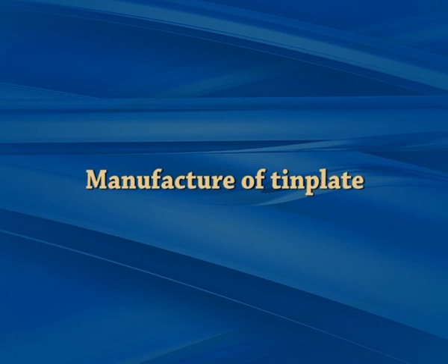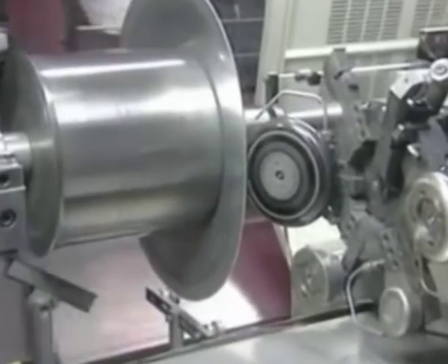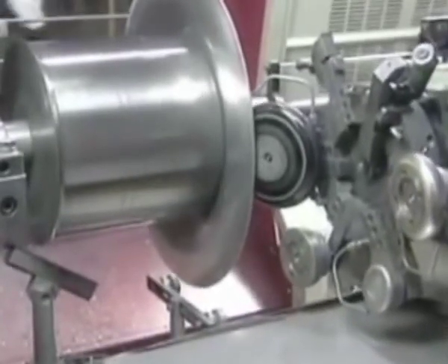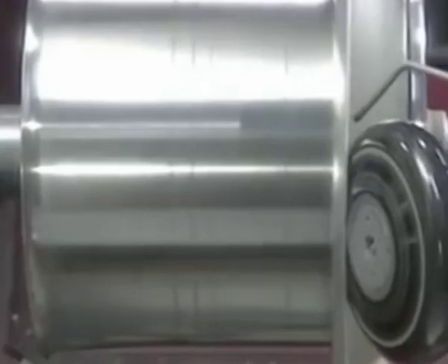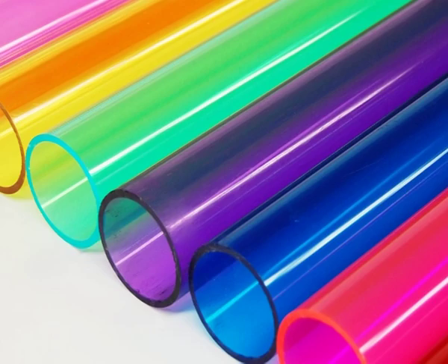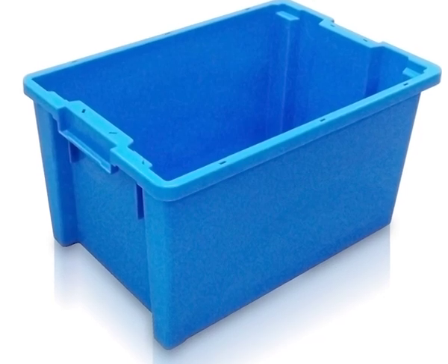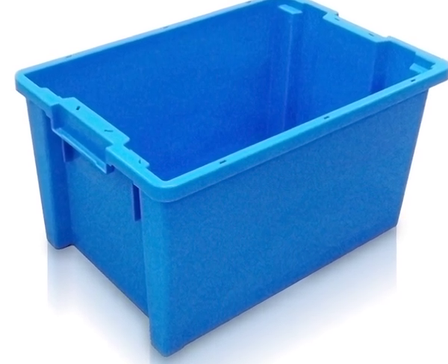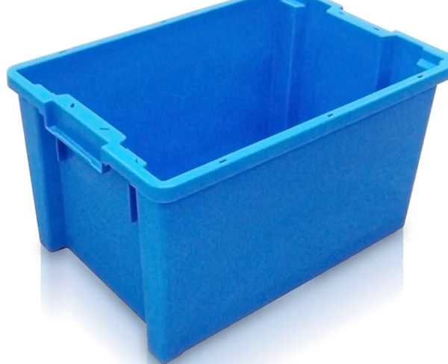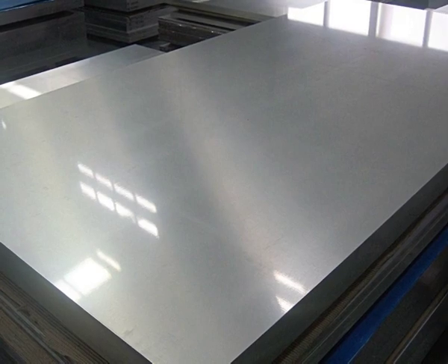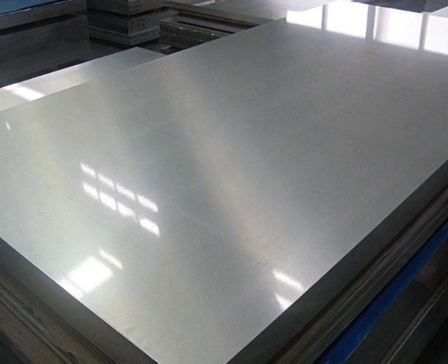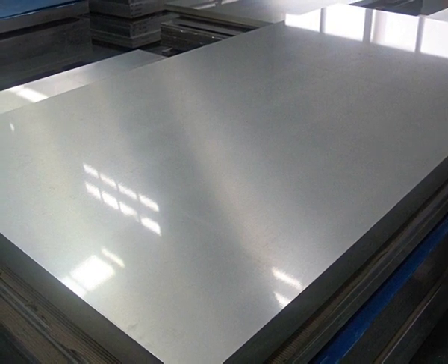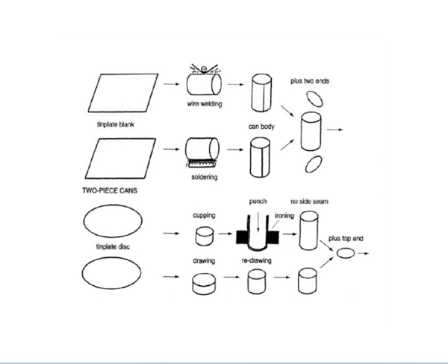Manufacturing of tin plate. The technique of building up metal containers from sheet by means of seaming confers one advantage over glass and plastic in that right angles can be easily achieved. Blown glass or plastic containers require radius, particularly at the base of the container, in order to avoid excessive thinning. The use of sheet material also allows decorating before container fabrication instead of after, with fewer limitations than for processes applicable to finished containers. In figure 1, you can see the process of tin plate manufacturing.